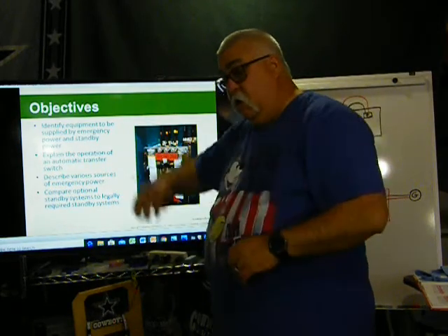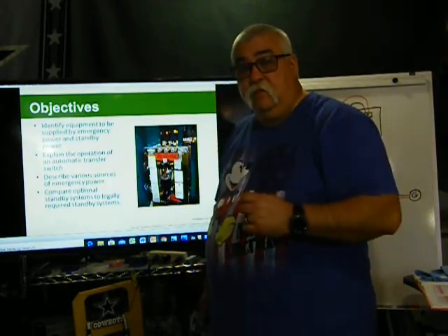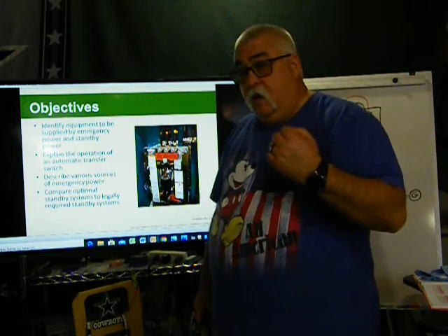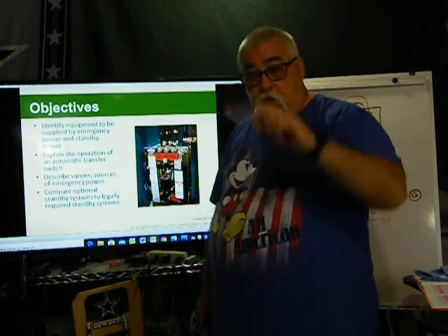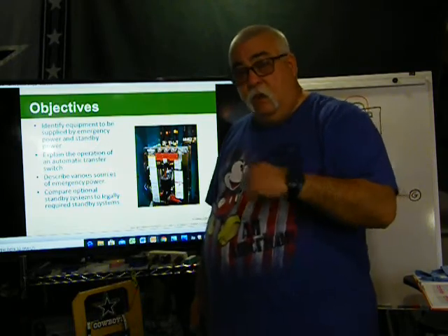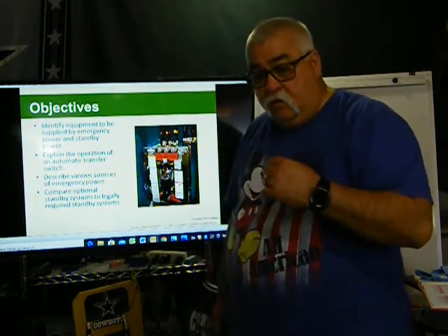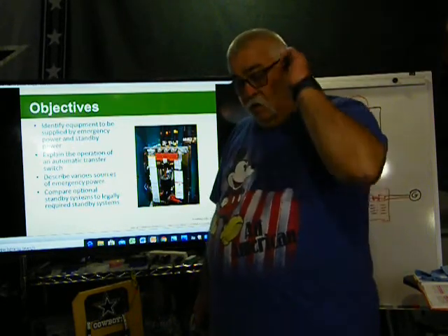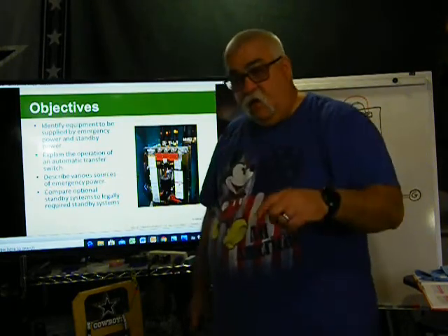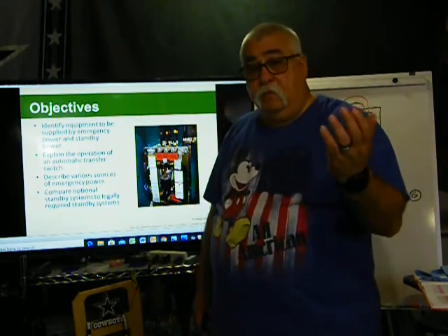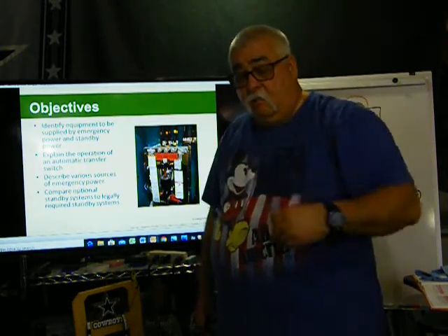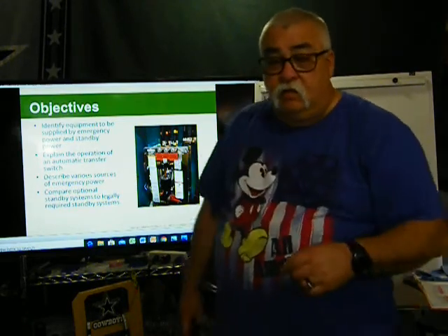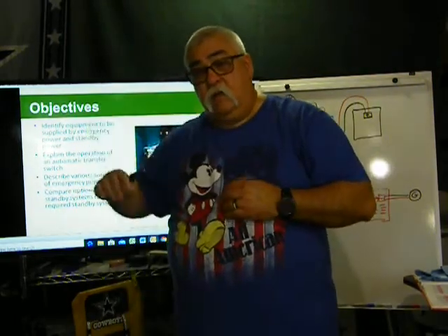So we go in there, we test it and let it run for about 15 minutes. If there were multiple, like we had one generator and it had 3 ATSs, I walk over to the first one, turn the generator on, transfer that one over, go to the second transfer switch, ATS, which is automatic transfer switch, click that one into test mode, then go to the third one and hit test mode. Then I come back around to the first one, transfer it back to normal power, then the second and third. Once the loads were removed from emergency power, it sends a signal to the generator, and the generator idles down and shuts itself off.